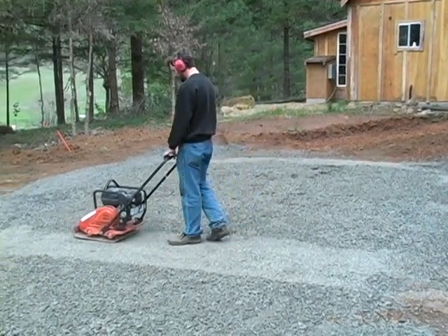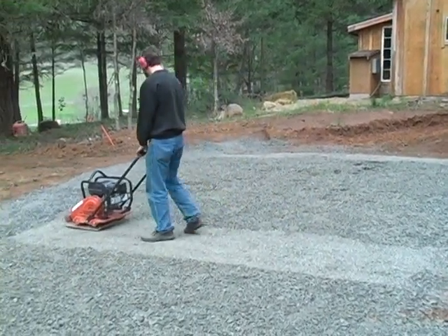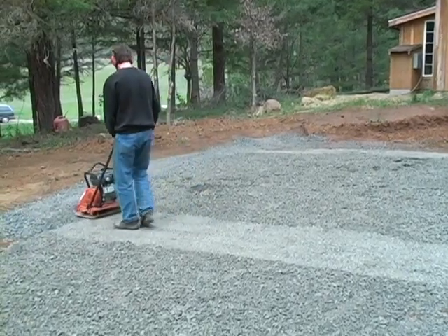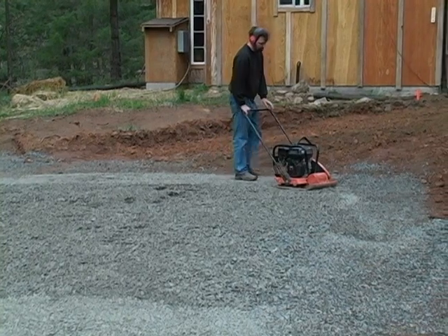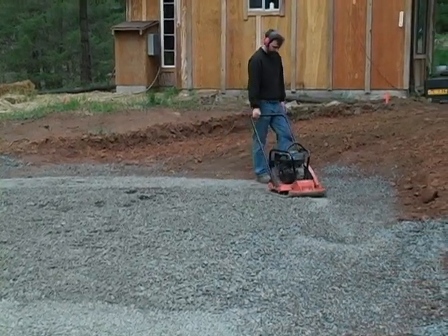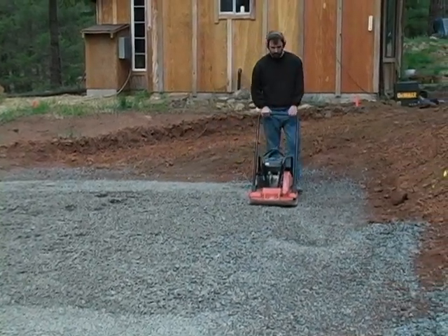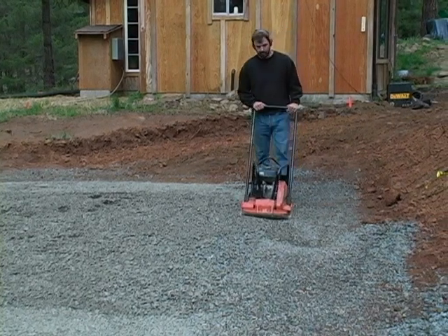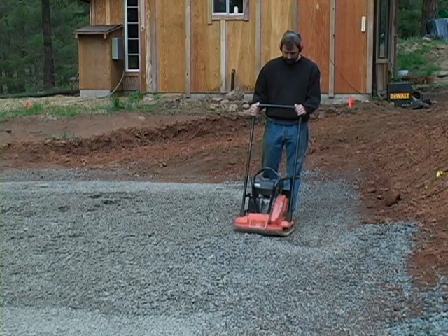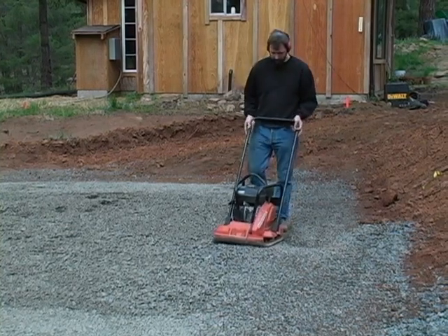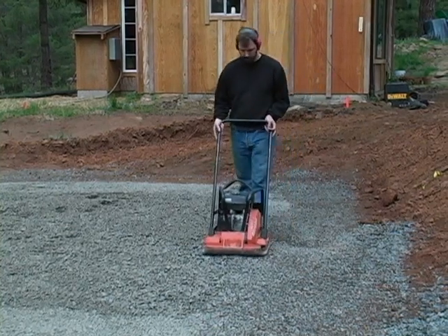By the nature of the compaction and the way the plate compactor works, it moves itself forward slowly as it compacts. So if you have it tethered to the center point, it'll actually slowly work its way around in a circle and wrap itself into the center. Then you can go back by hand and square out the corners and finish up the very center spot once you've pulled that stake. This allows you to work freely on the site on other aspects of things you might want to do rather than being stuck behind a machine the whole time.